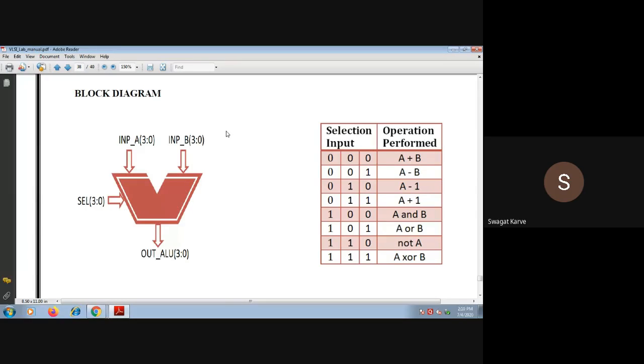So you can have the 2 inputs, each input of 4 bit, input A and input B are also 4 bit. Then the next question is, there are different mathematical and logical operations, right? There are addition, there can be a subtraction, there can be a division, or if you consider the logical operations, there are ANDing, there can be ORing, there can be a NOT of input, or A XOR B, A NAND B, A NOR B, anything, any logical operation you can perform.